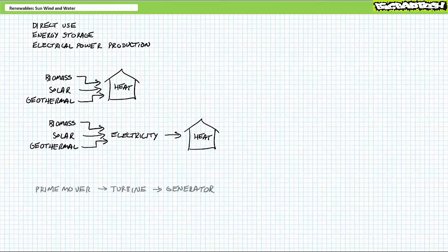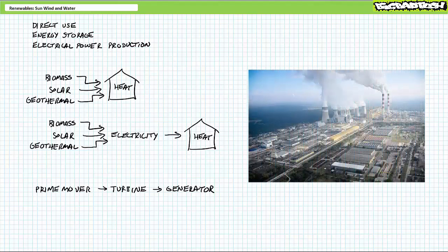at all. Historically, electrical power generation has involved some prime mover using a turbine to turn the rotor of a generator to export electrical power for use. A prime mover is some outside mechanical power source that could take the form of expanding steam, falling water, or moving wind. In this fashion, the mechanical power of the prime mover is converted into electrical power. For example, a coal-fired power plant burns coal to heat water in a boiler to produce high-pressure steam that forces a turbine to rotate.